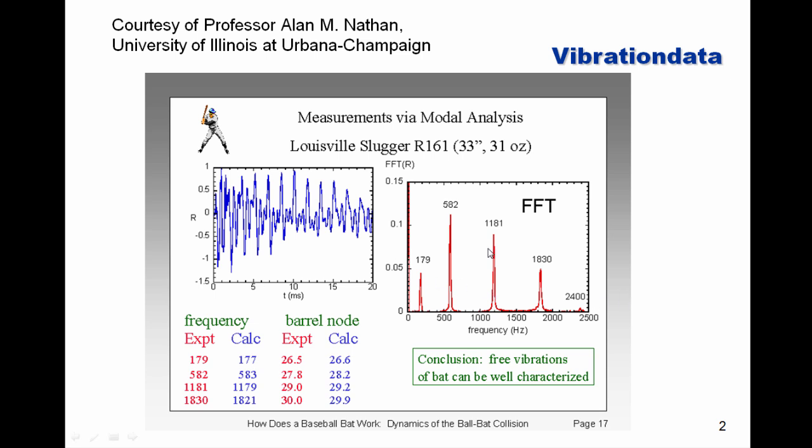So one of the tasks we have at hand is to come up with a mathematical function, a transformation, in other words, to get from the time history on the left to the spectral function on the right. If we know what the spectral function is, it can help us to understand, for example, the natural frequencies of an object in its response. It will also help us to identify the forcing frequencies. For example, if we have a helicopter or some machinery with rotating or reciprocating parts, we can pick out the forcing frequencies or the imbalance frequencies from the rotor.